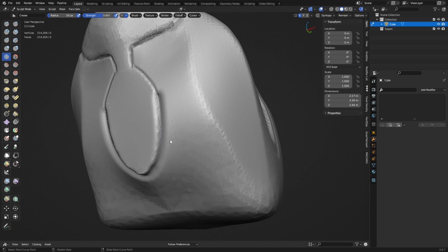Press A twice, X, and you can delete that, and you can go around and do more of those all day long. So it's a fun little tool there to make nicer strokes, perhaps, right?